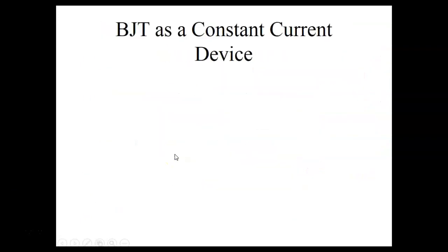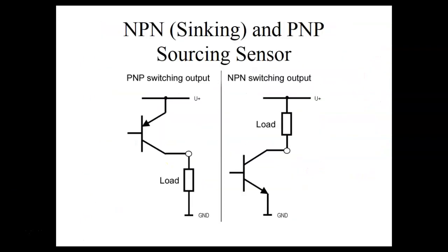So this is switch design. By the way, we talked a little bit about this in sensors, in digital sensors; basically you're using saturated switches for a solid state sensor. So all these transducers we're looking at, the photoelectric transducers, your inductive and your capacitive transducers or sensors, these guys, as we talked about, are either sinking or sourcing. Well, inside the sensor, it's either going to use a PNP or an NPN transistor.